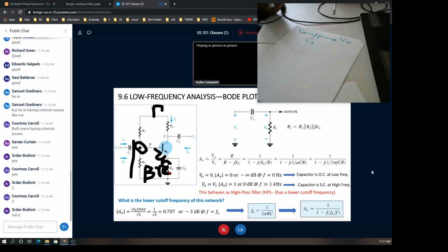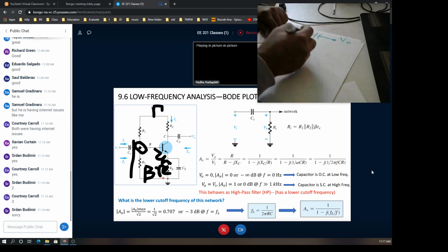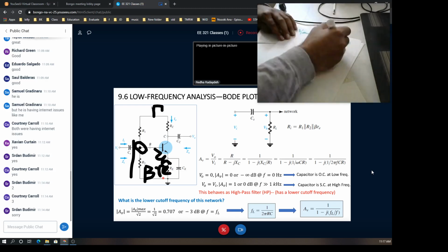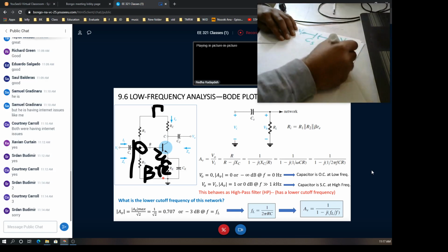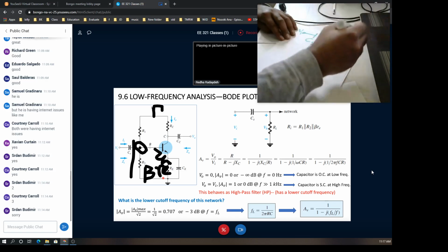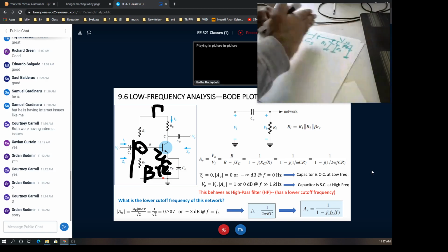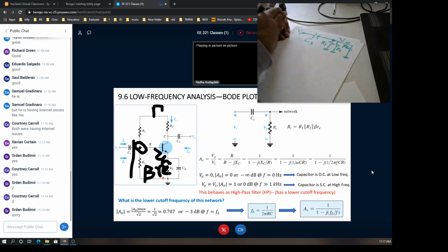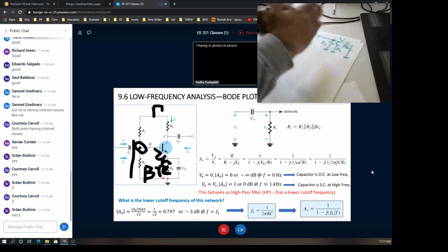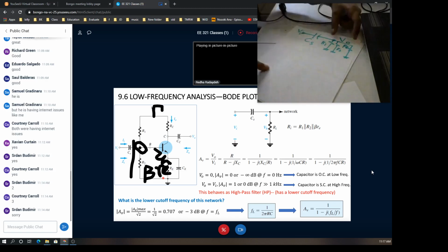We complete the AC circuit by adding the R1 resistor here and the R2 resistor here in parallel, and the resistor representing the diode between the base and emitter, whose value is beta times Re. This is the input portion of the AC circuit. So the output voltage after the capacitor is the voltage measured across these three parallel resistors.